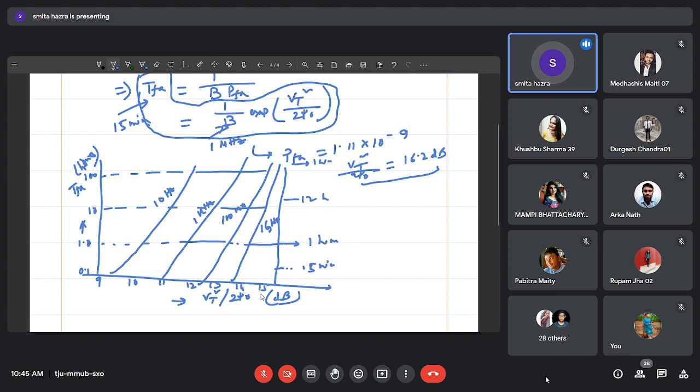And here on the horizontal scale is the ratio of the decision threshold and the RMS noise power. So where the graph is touching, that means 12 dB, 11 dB, or between 9 and 10 dB, at 14 dB, here it is near 15 dB. So these give us the corresponding ratio between these two and the false alarm timing. Because here we have plotted in terms of hours, starting from 0.1 hour, it can extend up to 10,000 hours, so the mapping goes even for the year also.